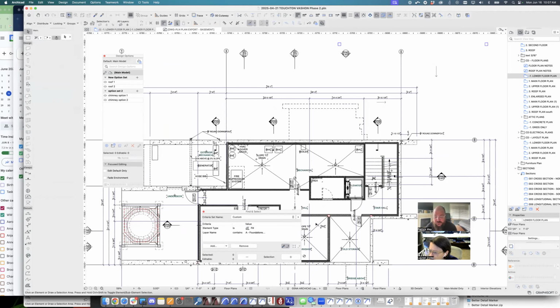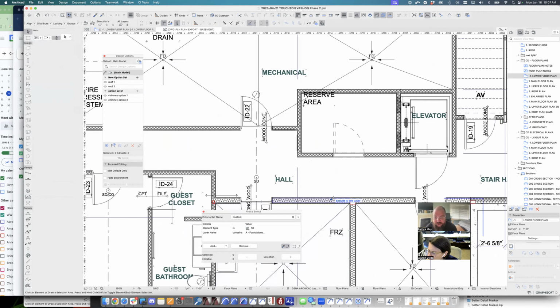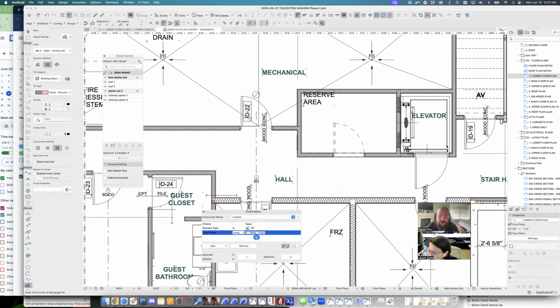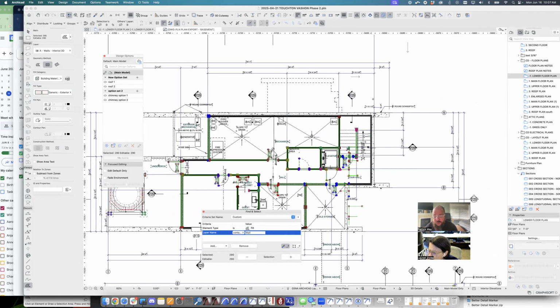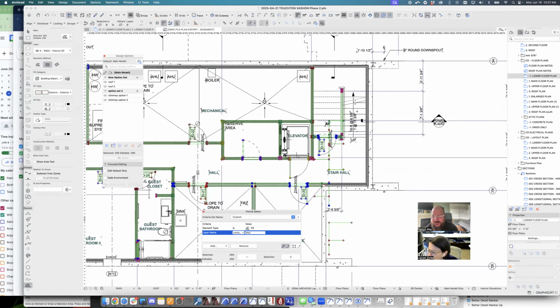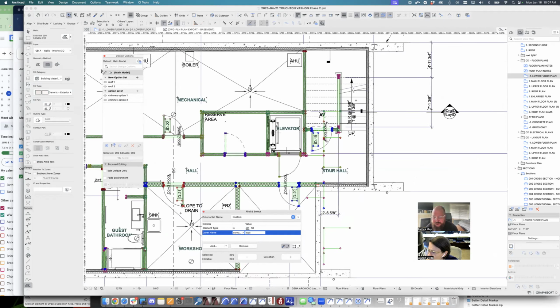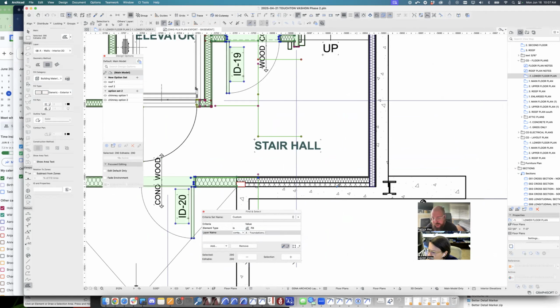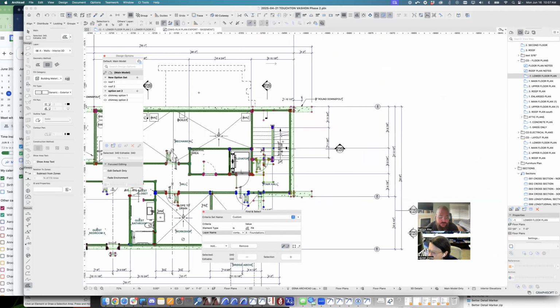Let's go to fills where the layer name contains wall. I'm going to grab all the fills that are on walls. And you can see it's a little bit easier because my foundations are not included, but maybe I want to include those, because some of these fills actually do run across. So we'll include those as well. And then we double check here. So we've got 340 fills.